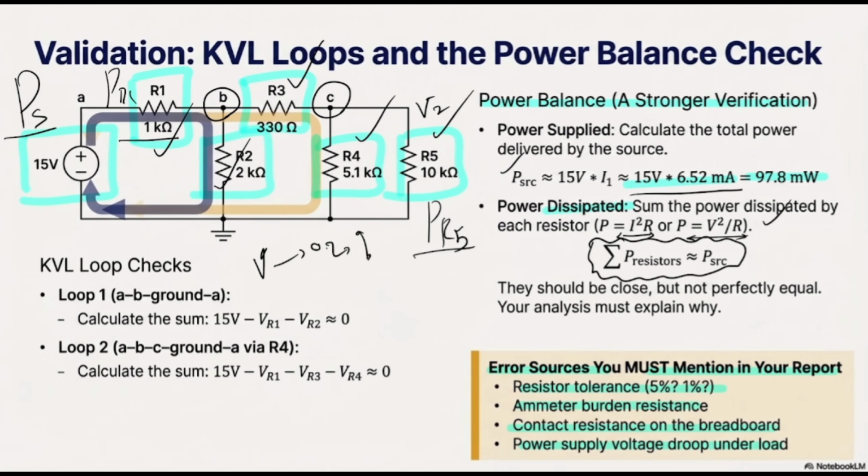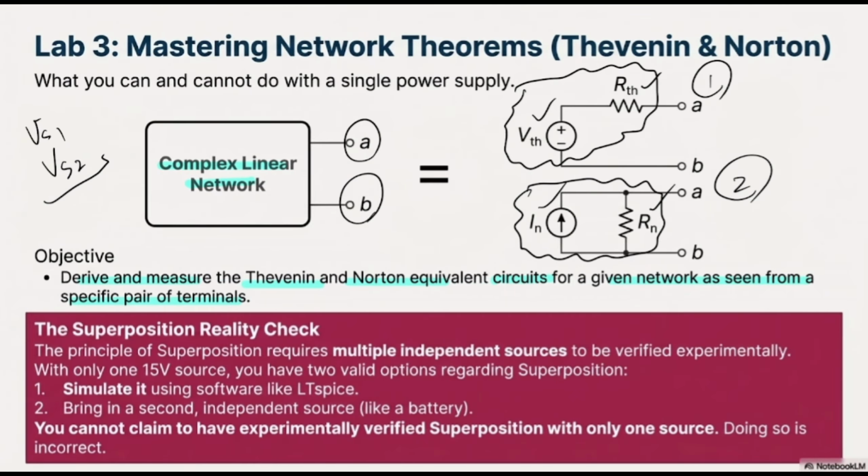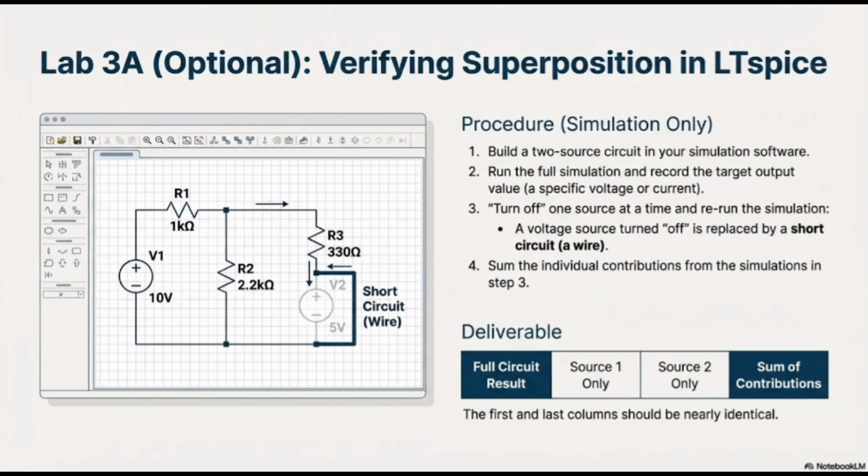Then we may have a current source. In order to get rid of the current source, I should be 0. As we all know, I is 0 only when you have an open circuit, so you have to make it an open circuit. At the end, when you find all of the numbers, based on the direction of voltage or current, you can add them up or subtract them. That's the superposition method.